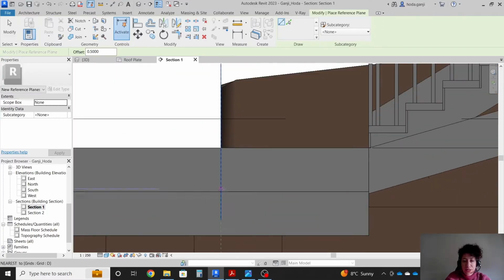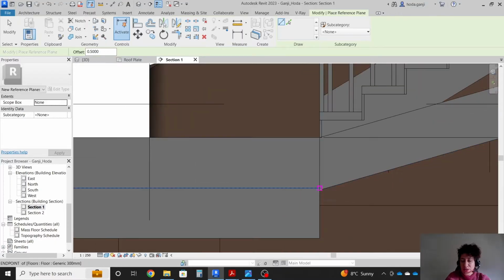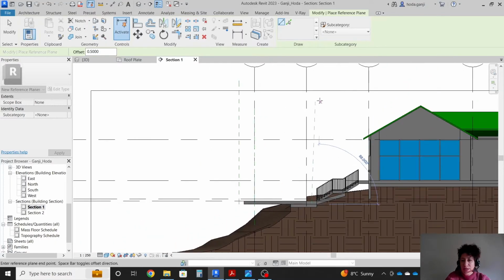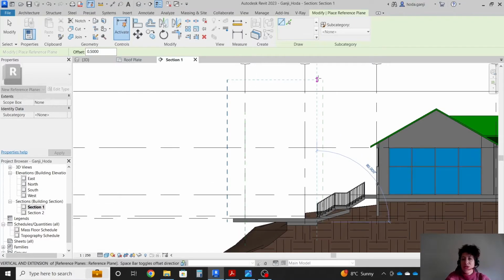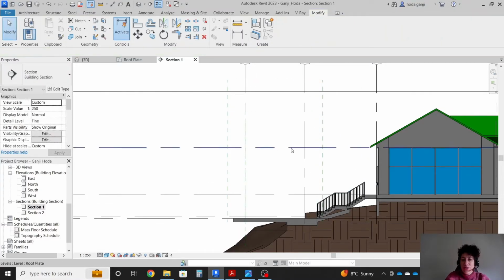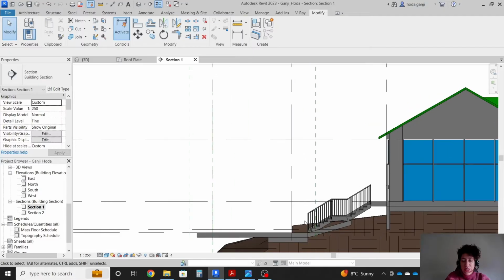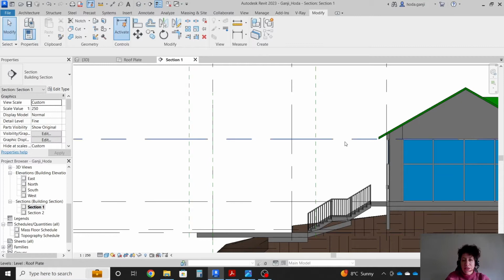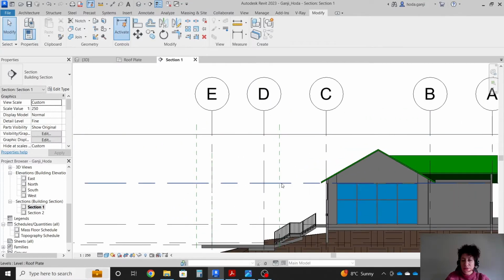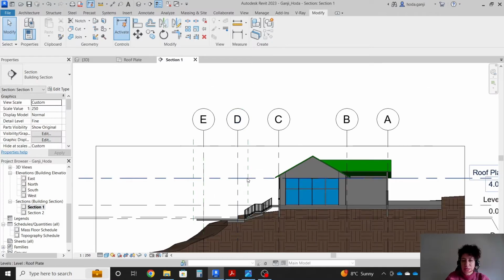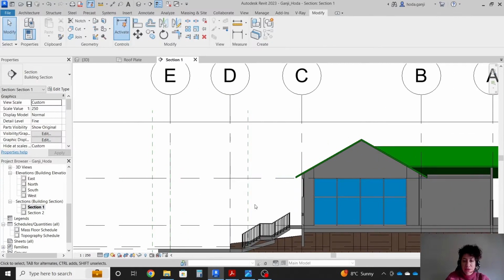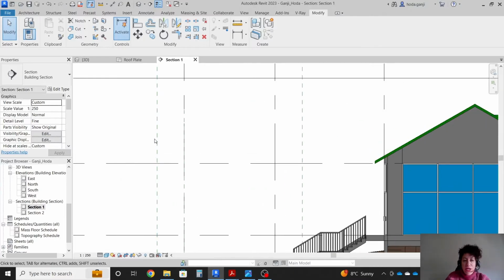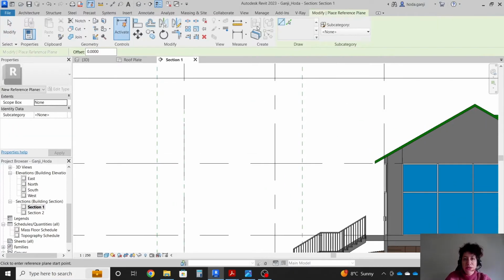it actually ends here. The rest of it is the stairs, but I can go till here, so it's gonna cover that part as well. Hit a space so it's on the right location. So my roof is gonna be around here. Let's say maybe one side of it is gonna be about 1 meter higher than the other side. I want to start one side of it on the intersection of roof plate and the reference plane that I just drew. On the other end, I want to go with another RP.